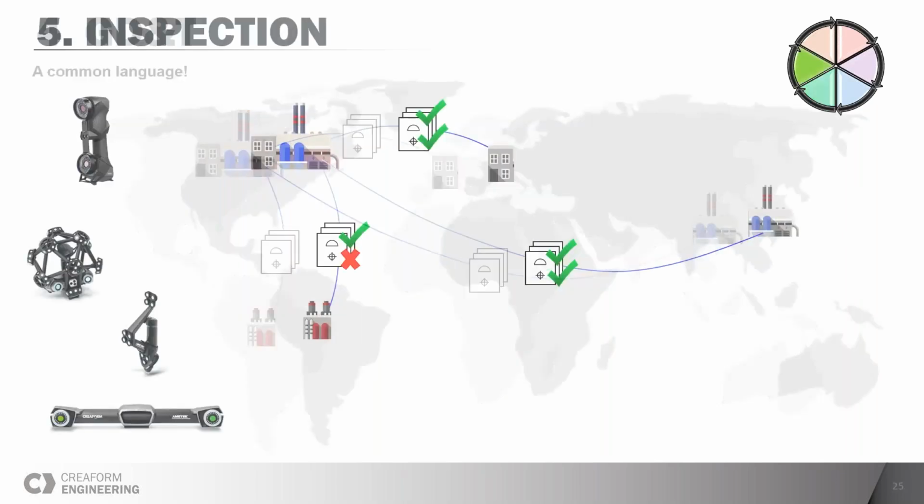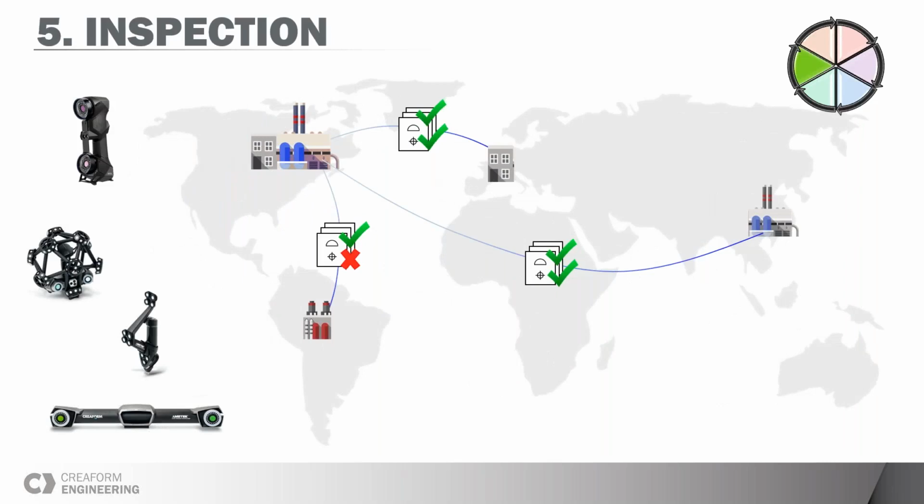So the next steps happen during the manufacturing process, and it's the inspection of the parts. GD&T was first used to communicate the need, but now it's used to control the part and assess whether or not each part will allow us to meet the final requirements. So this is the target we evaluated in the analysis step. If we have done a good job of documenting everything from the start, we can even know right away which final functional requirement will be impacted by a specific dimension that is out of tolerance.